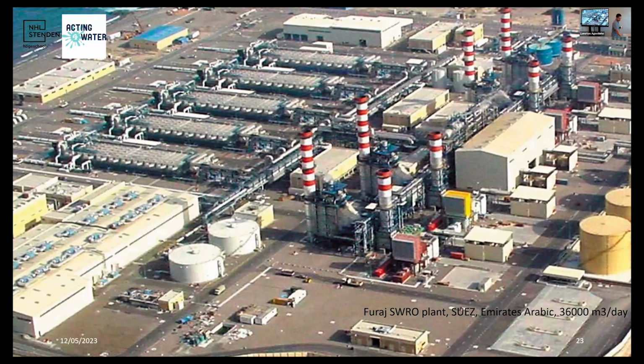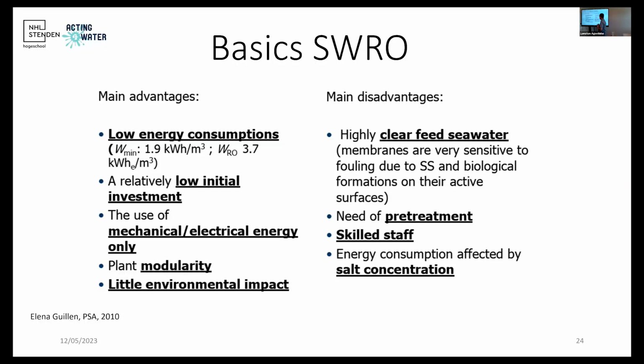The main principle of seawater reverse osmosis is that it is a membrane system. For membrane systems, you have to think in a very simple way. A membrane is like a cloth. If you look very closely at your cloth under a microscope, you will see that it's not completely closed. You have fibers, and in between the fibers you have spaces, so it is porous. So imagine that you want to put some water on the cloth. Everything suspended in your water that is bigger than the spaces will be retained, and everything which is smaller passes.